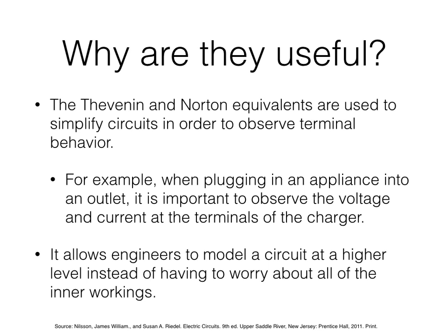Why are they useful? The Thevenin and Norton equivalents are used to simplify circuits in order to observe terminal behavior. It allows engineers to model a circuit at a higher level instead of having to worry about all of the inner workings.